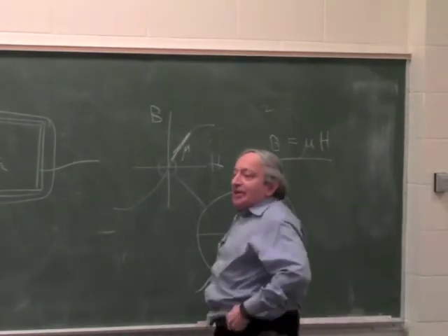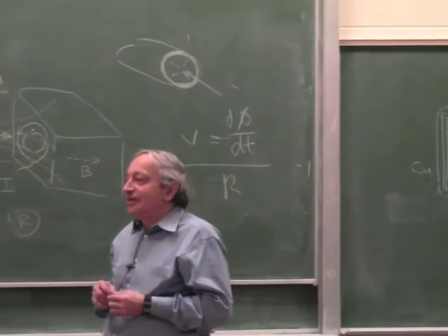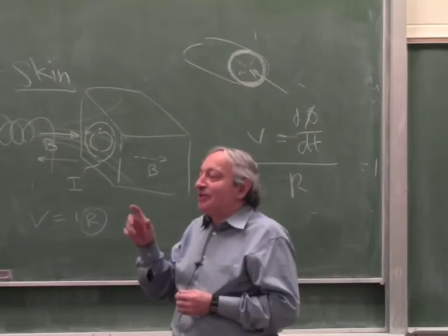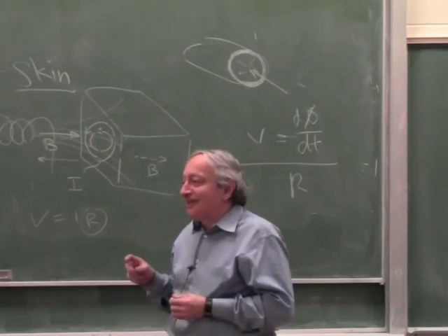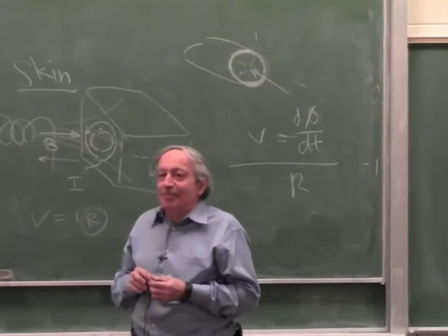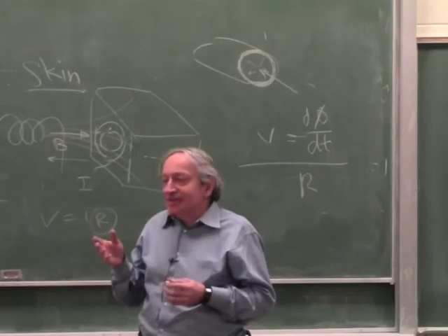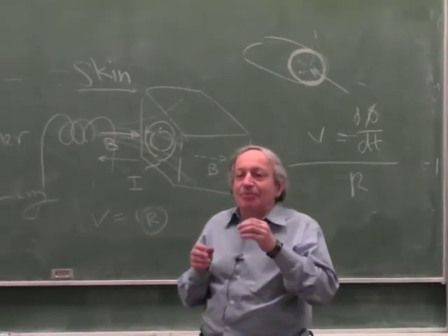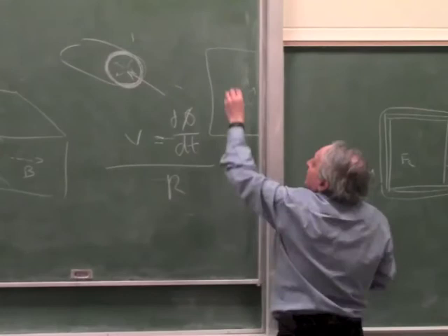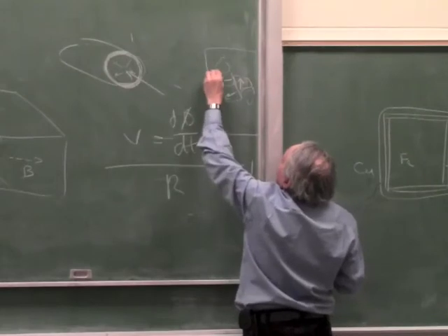So you have to think about how magnetism is formed in steel. Okay, yes? You need a certain amount of magnetic moments to line up. To line up what? In an orientation to your magnetizing force. Yeah, but what are you lining up? You are very close. The dipole? Or magnetic moments. You basically line up the domains. It turns out that in a material, of course, each atom has a magnetic moment, but the magnetic material is built up of many domains. So when you look at a piece of steel and you magnetize it, it appears to have random zones, and each zone has a different direction of magnetization.